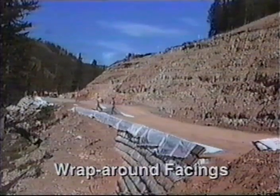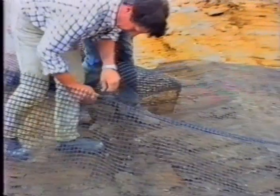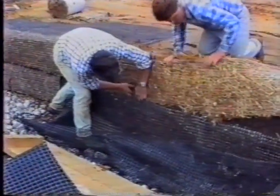We have already seen geotextiles used as wraparound facings for a steep slope. They are used similarly for geosynthetic reinforced MSE walls. Geogrids are also used for wrap facings, though some kind of covering or vegetation is needed to prevent the fill soil from passing through the grid apertures.